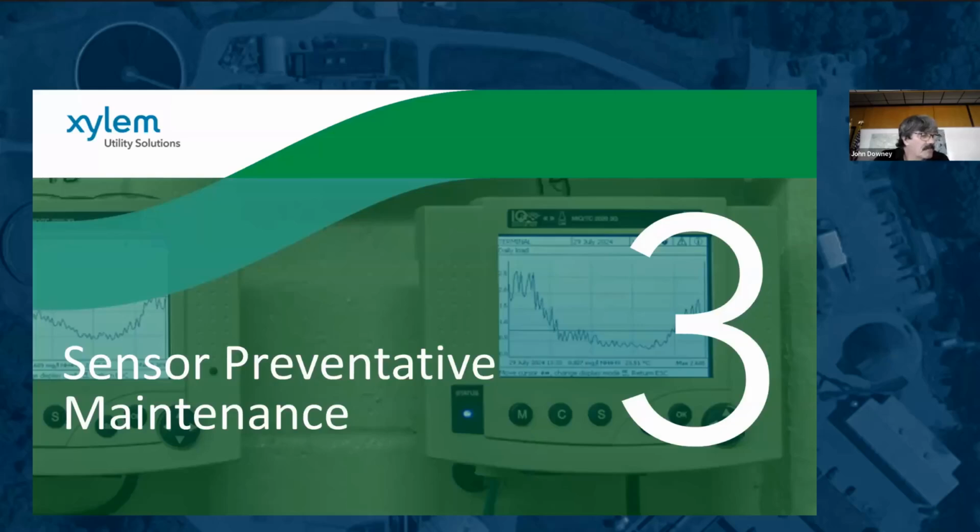Starting at the effluent of the plant, I walk to each sensor controller location, which has a display incorporated in it, to check the performance of the sensors since the previous morning. Basically, I'm looking at a graph for the last 24 hours, first to confirm that it is not a flat line, and even pH is not completely static, and that the range that's measured is plausible. Anything out of the ordinary lets me know that I may need to investigate further.